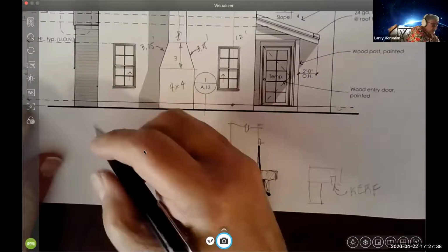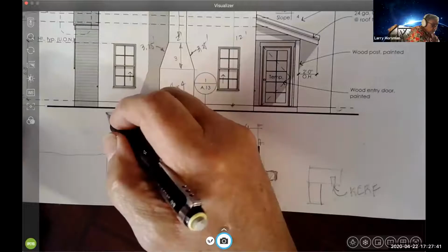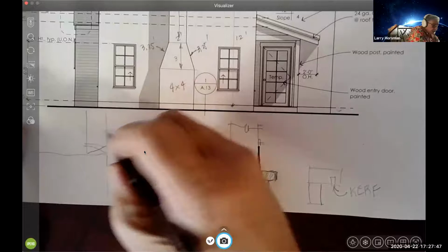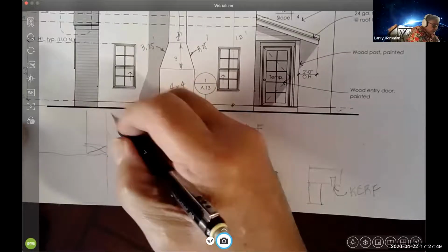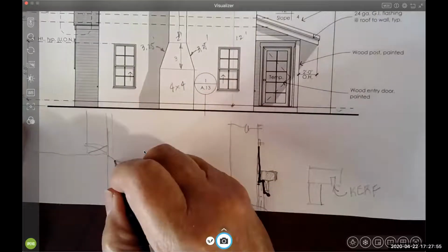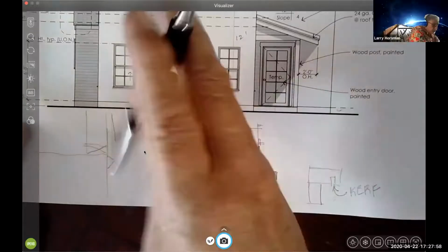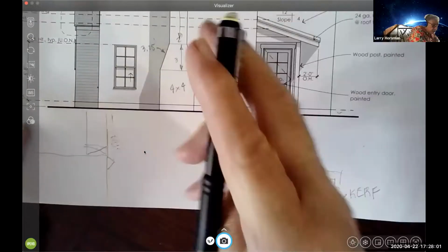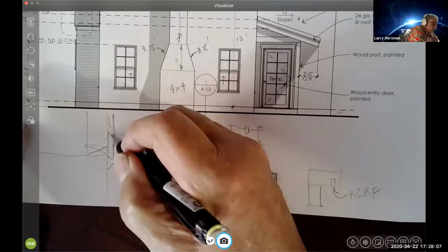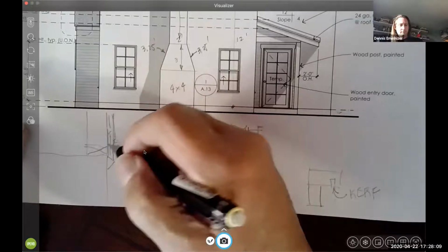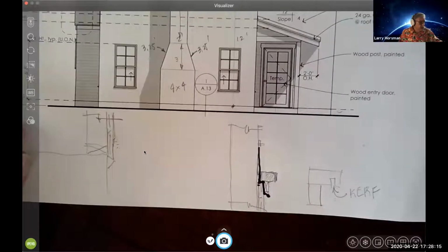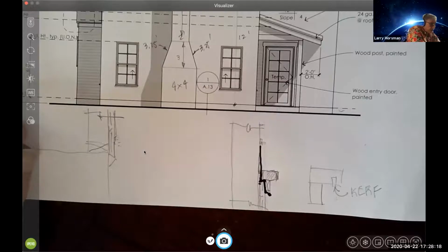Right. So we have the slab, sill plate, stucco comes down. Building code requires a weep screed. What is it, 5 inches or so? Yeah, it has a minimum flange width going up. I mean, it's pretty standard. So what we're going to have, usually you have line wire or stucco mesh. There's a bunch of proprietary systems out there too, but this is the screed.